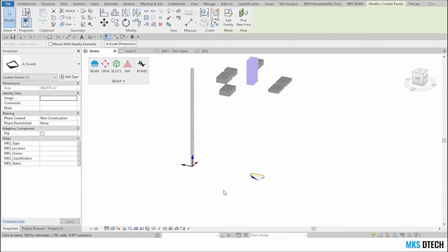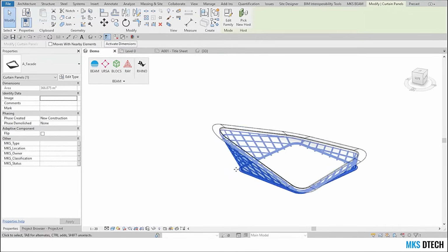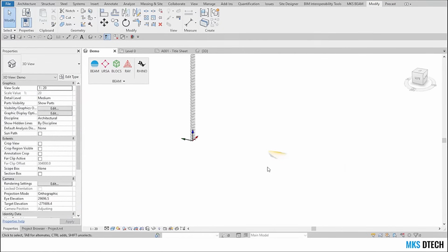Using loose geometry is convenient because it's faster, but of course using blocks is the best workflow because you see the insertion point of the families here, while if I had used a block, it would use the block insertion point, so the rotation would not be based on the center of the file, but depends on the stage you are at and what you're doing. Of course, different workflows are possible, but we always suggest to use Rhino blocks as much as possible.